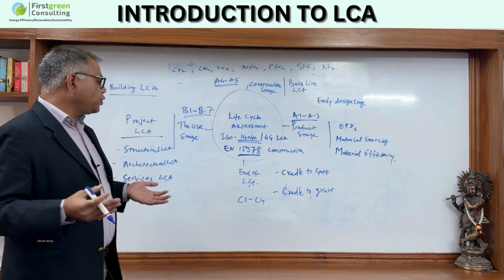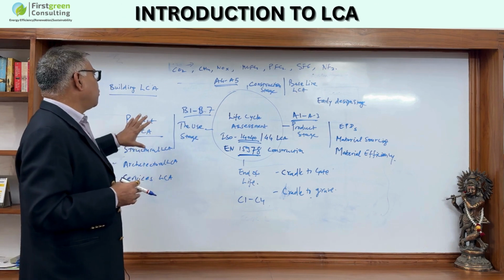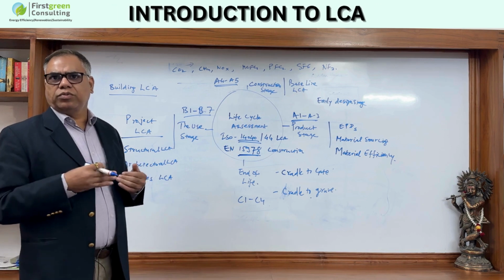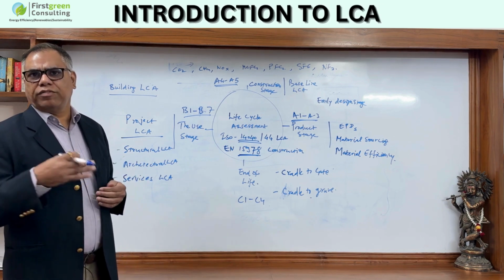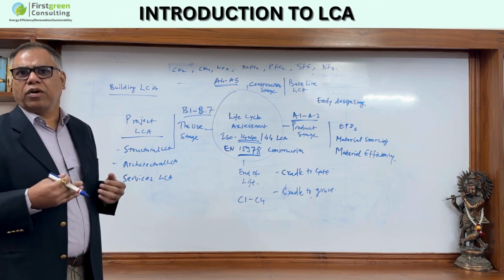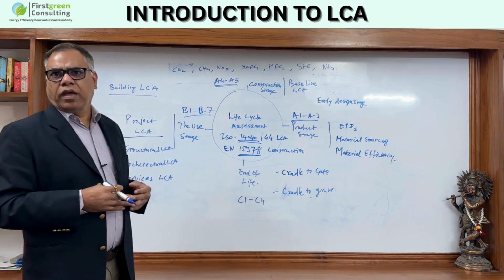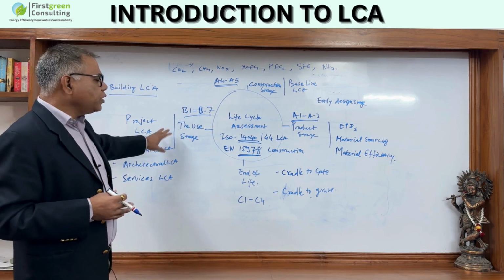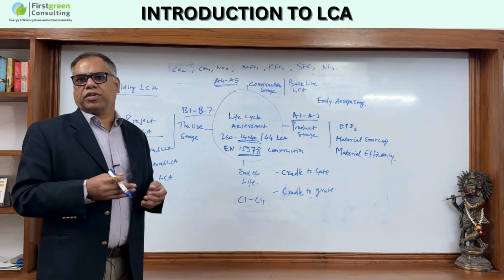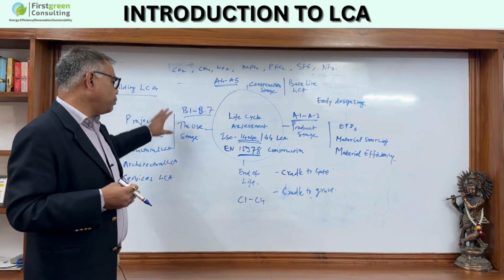When you do the emission accounting, you use various tools for doing this. We will discuss some of the tools because it's a very complex procedure. We will do a real case study and share the data for how we do accounting at the planning stage, the construction stage, and the operation stage. And not only the operation stage, if you are doing some retrofitting in the building, those are also accounted here. Suppose you are changing the facade, so those operations and retrofits are also part of the use of the building.